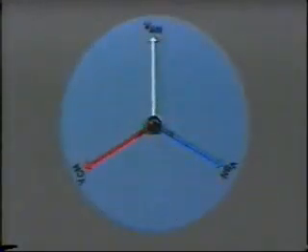So for the purpose of study, it's convenient to hold the rotation and fix all of the values, just as though we are rotating with the phasors. For example, let's look at this simple representation of a single-phase voltage and its associated current. The length of this line is proportional to the voltage, and similarly, current is represented by this line here. Normally, the magnitude represents RMS value of voltage and current, the values indicated by most meters.